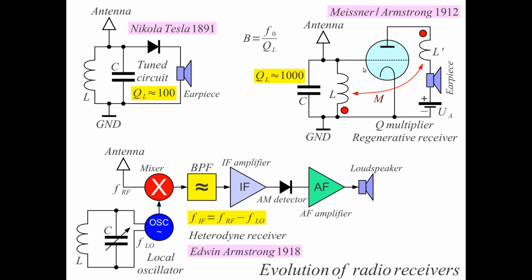So it was just a matter of electrical design to actually produce a local oscillator with one of such oscillating receivers, and the other receiver acts as a mixer to convert this radio frequency signal down to an intermediate frequency. What is the advantage of doing this?